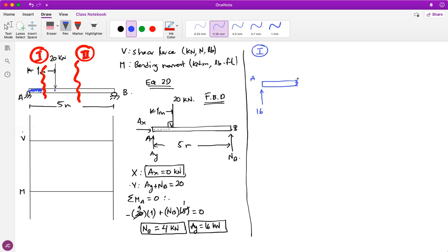What I will see in this chunk of the beam is the point O, that's the typical way to call it. I will see a shear force there, V, and I will see a bending moment, the M over there. These 3 guys, O, V, and M, need to be put all the time that you do a new section, okay? All these guys are gonna appear.